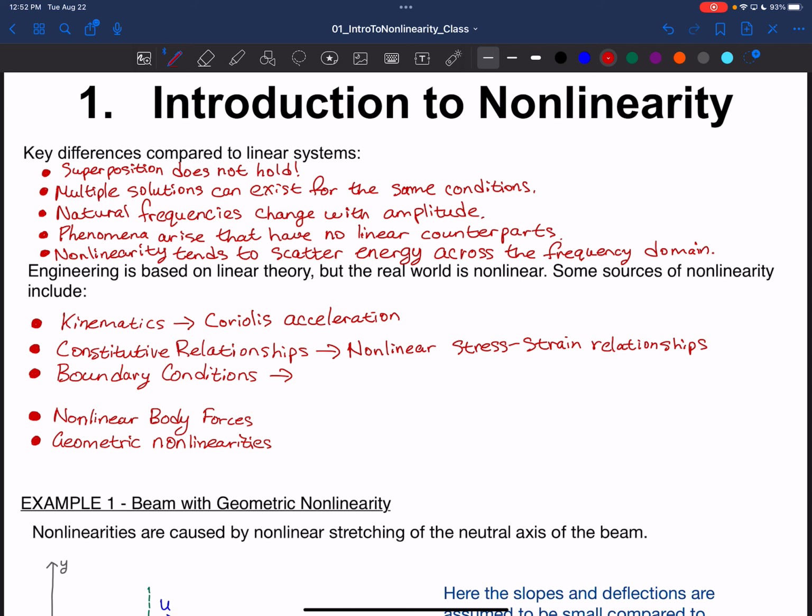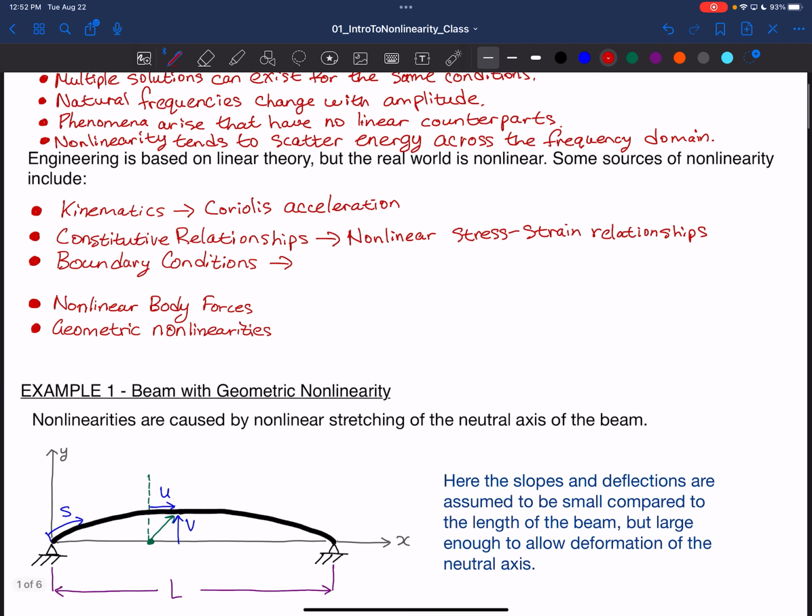Nevertheless, we can say things like vibro-impacts, which is the strongest type of nonlinearity. Clearances are by far the most common source of nonlinearity, and I believe we'll talk about clearances at some point in this lecture. Well, if not, we'll talk about it at some point. Any kind of loose connection as well.